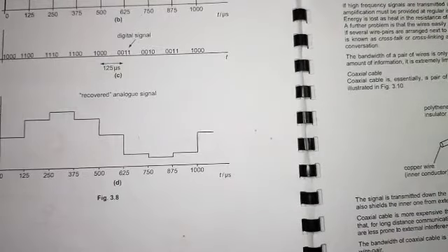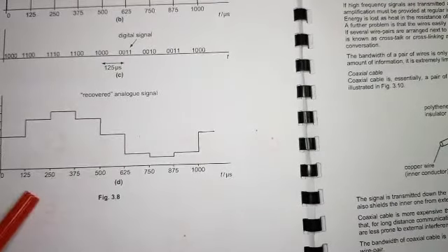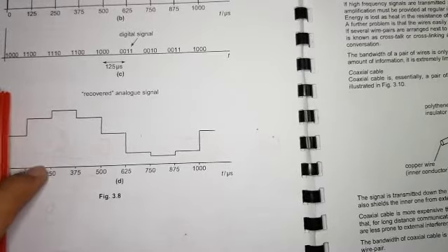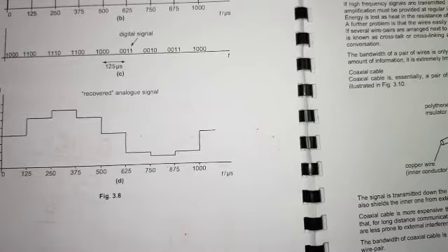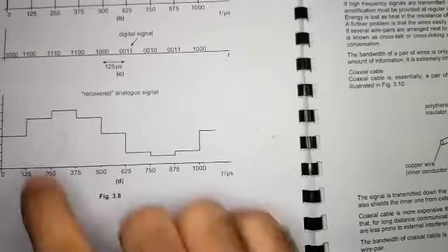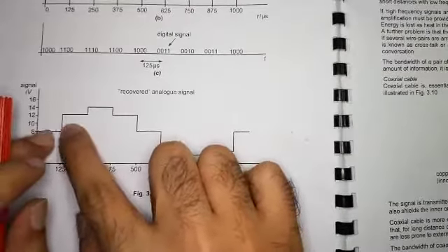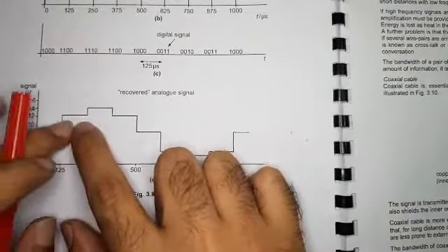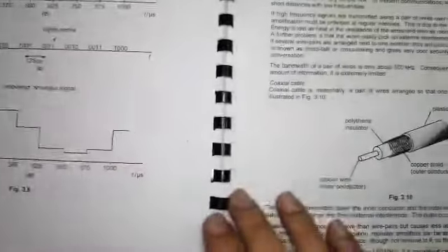Currently we're sampling at 125 microseconds. To make the steps narrower, you would sample at, say, 100 microseconds or 25 microseconds, right? So that makes the steps become smaller. The width of them decreases and the height of them decreases if you increase these values, right? So that's basically how you do this. There we go with that.